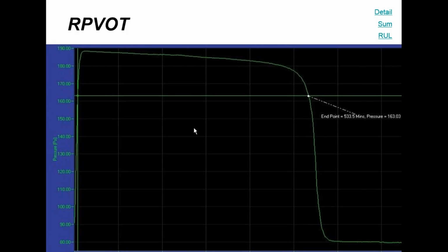This is a good graph. I like taking a look at this, and it's kind of interesting to look at. But here's the starting point of our test. So we pressurized it to 90 psi, and we started it here at 0 minutes. And then within dropping it in, we know that whenever we have gas, when we heat it, it'll increase the pressure if we have a fixed volume. Well, that's what happens, we have a fixed volume, and as you can see, as it heats up, the pressure really increases. In this case, it looks like it gets to about 188, 187, somewhere around there.